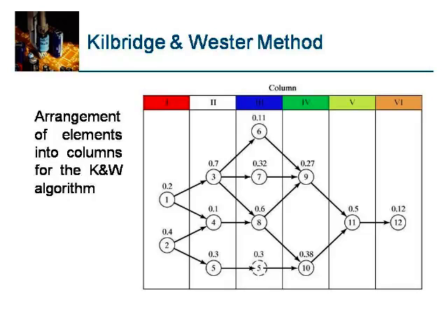Then go to the next set, allocating these elements to the various stations. But automatically, from one column to another column, if you select, the precedence relations are followed, and thus the precedence constraints are not violated, and assignment is done. This is Kilbridge-Wester's method.